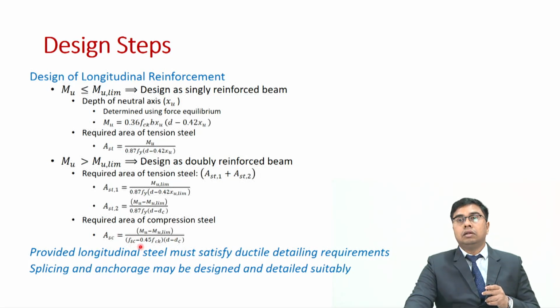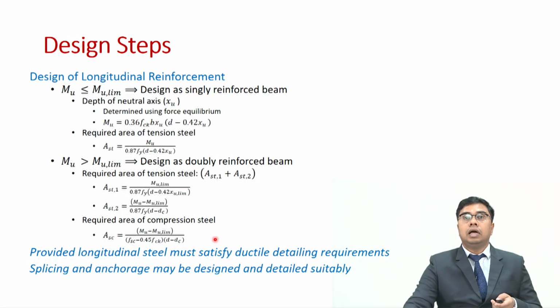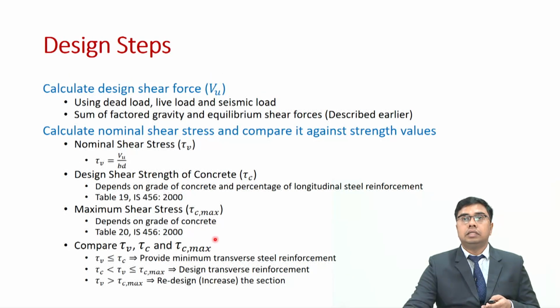Here we shall look into various terms as we go through the example problem, and after designing the longitudinal reinforcement, we need to check that the provided longitudinal steel must satisfy ductile detailing requirements as listed earlier. We should also be designing splicing and anchorage suitably. Then we will calculate the design shear force.